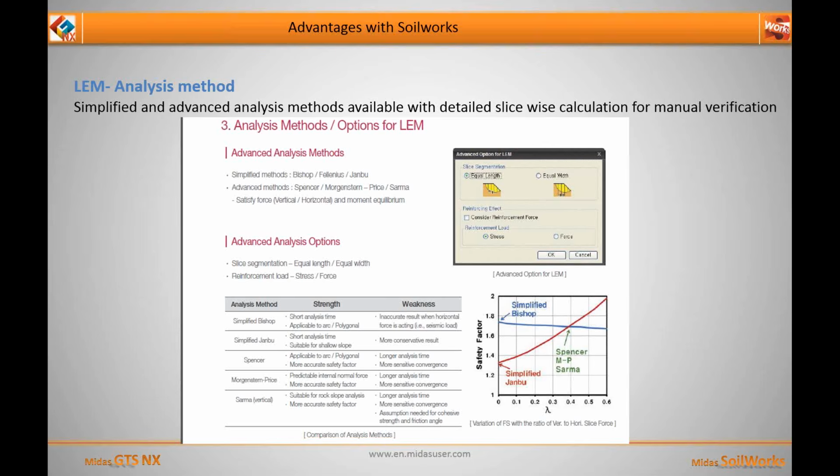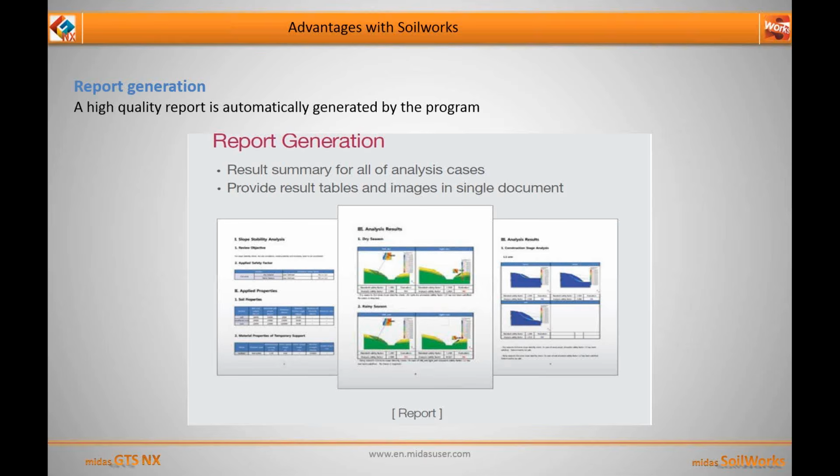In the analysis methods for LEM, we have both the simplified and advanced analysis methods with detailed slice-wise calculation for manual verification too. You can see we have the simplified methods like Bishop, Janbu, and also the advanced analysis methods like Spencer, Morgenstern-Price, and Sharma vertical. Also, a high quality report is automatically generated by the program, which could be used by you to directly submit a brief summary of what you did to your boss.